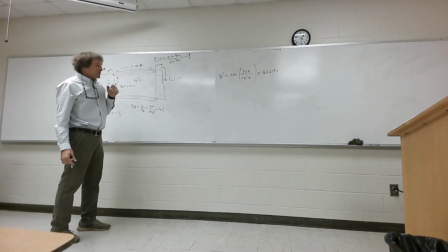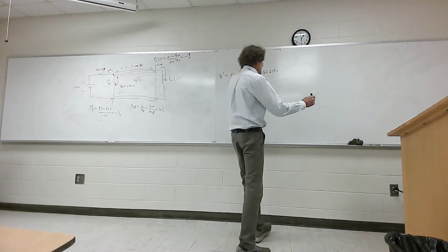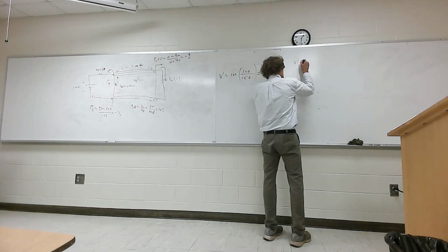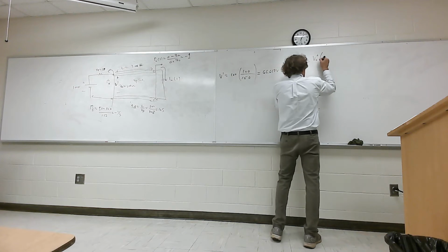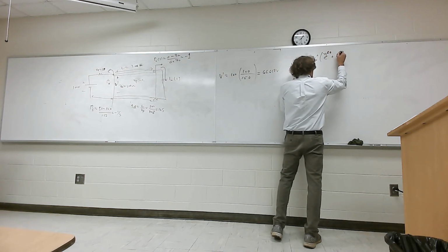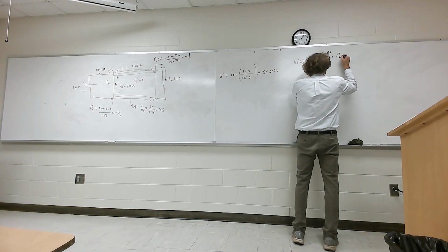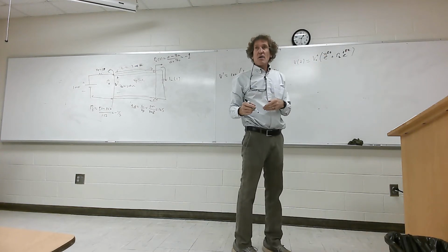Now, if you take a look for a second at the equation so you can appreciate this, when you had V anywhere on a transmission line, that was equal to some V naught plus times e to the minus j beta z plus the reflection coefficient at the load, right there, times e to the plus j beta z. Y'all remember that? That's the voltage anywhere on the line.